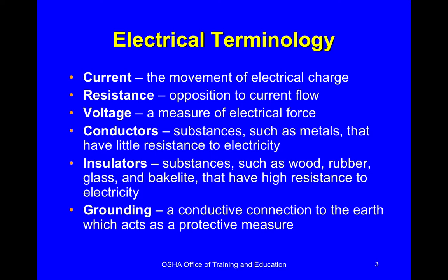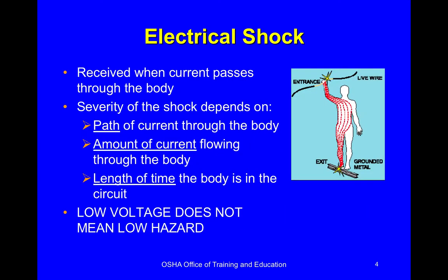And then grounding, remember that that is a conductive connection to earth, or the ground that we stand on. Remember that electricity is always trying to seek ground. So you have to give it an easier path to take so that you don't become the path to ground. So electric shock is received when current passes through your body. The severity of it is going to depend on the path it takes, how long you're in contact with it, and how much current is actually flowing through you.